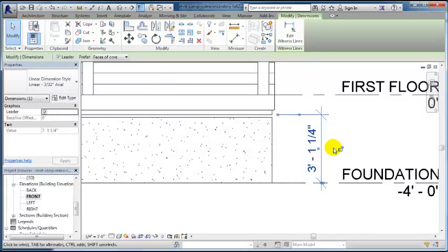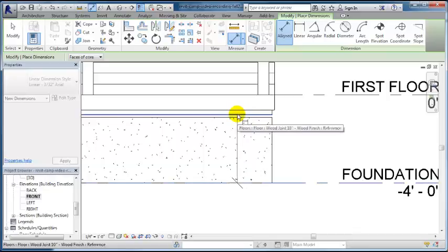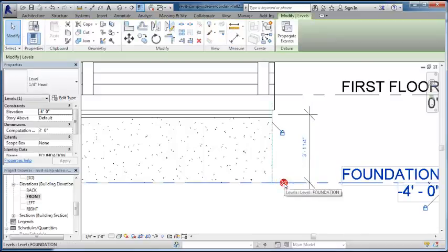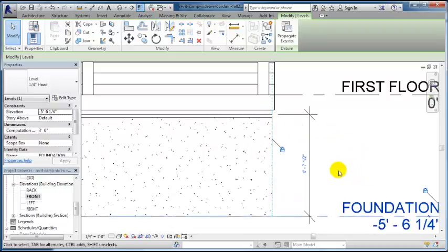All right, I figured out what was wrong. I didn't realize this, but we can't make adjustments because we were using the bottom of the wall and the top of the wall. We actually have to use something that's not part of that entity, so instead I just am snapping to the floor system, and I'll do a little bit of math. I want to add 1.5 inches to whatever I put in here for a dimension. So now I can select that foundation, and that makes that dimension active, and I can type in 4 foot 7.5 inches, because that would be the 4 foot 6 plus the 1.5 inches for the mud sill, and that gives us 6 inches above grade and then a 4 foot depth.